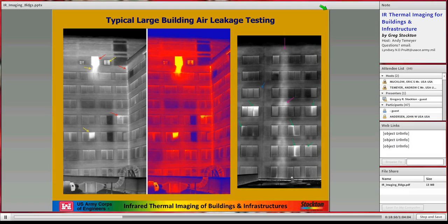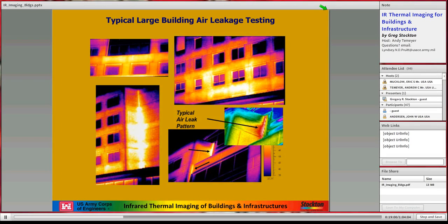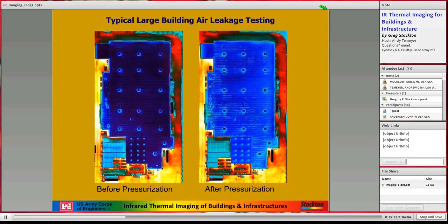This is a VA hospital. Old building. Tremendous amount of per square foot cost for heating and cooling. With an infrared camera, you can see the obvious that nobody else can really see. They got uninsulated steam pipes in the wall, as shown on this right-hand side picture. They got vents blowing superheated air out. They got windows open. All sorts of things.